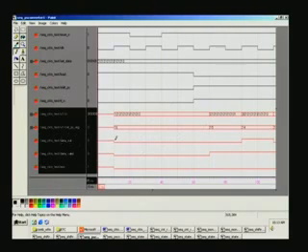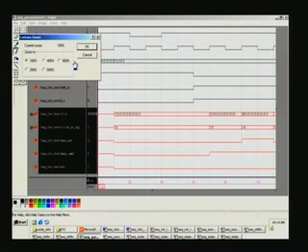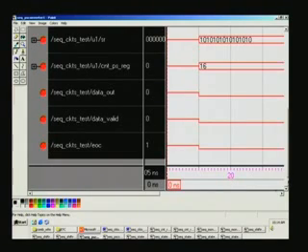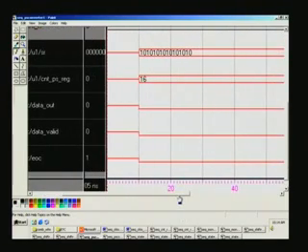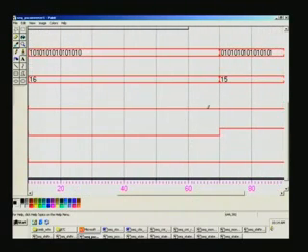Data out is here. To start with, it is all 0 here. Okay, I will just zoom this so that you may know. So this is the shift register, and this is the counter, this is the data out, and a data valid and end of conversion is also here. All these are 0 here, data out, data valid and end of conversion, right at the point of loading the value.